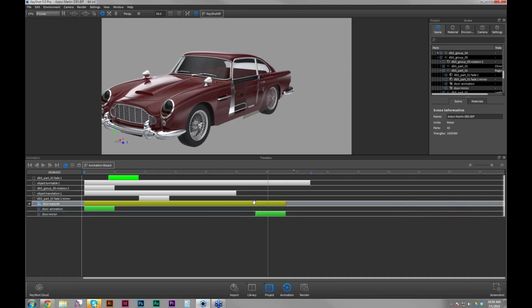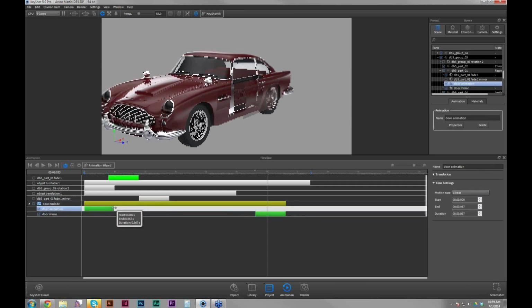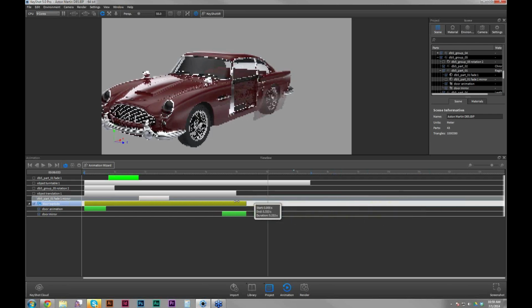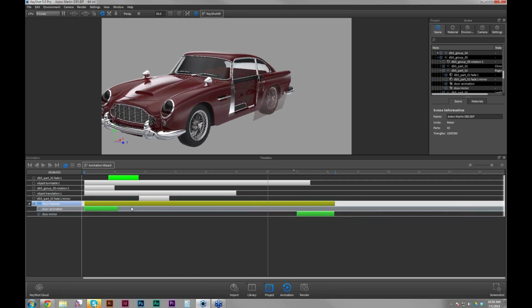And what's really great about this is if you know for a fact that these two animations need to live within X amount of duration, instead of interpolating or trying to figure out how long each one's going to need to be equally, you can highlight the folder node and just drag that down, and it'll automatically reduce or increase the size of the animation nodes located within them to be equally. So as you can see, as I'm dragging it, the nodes get longer and shorter automatically.